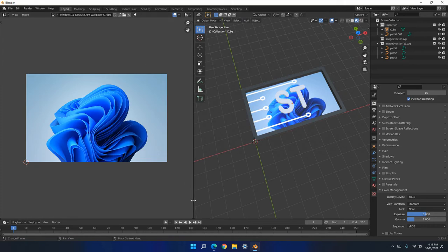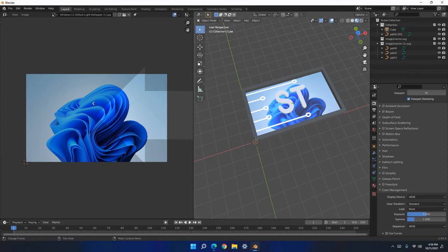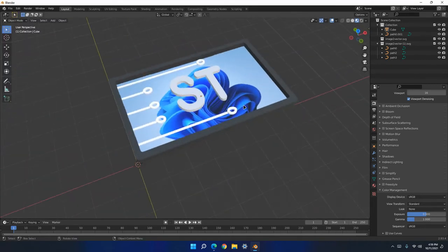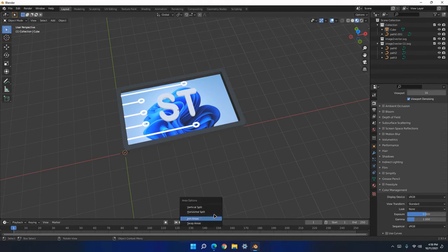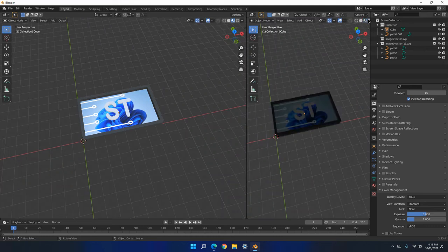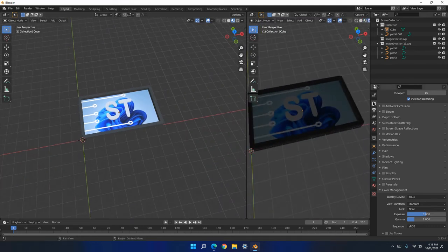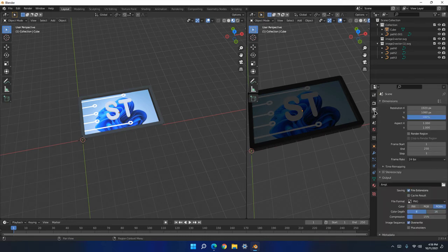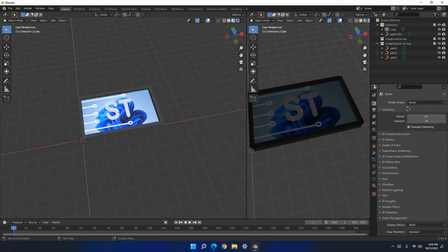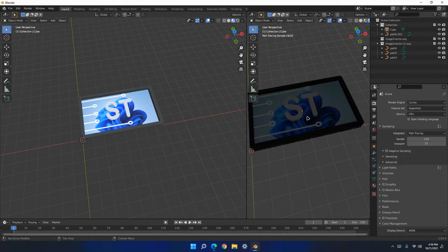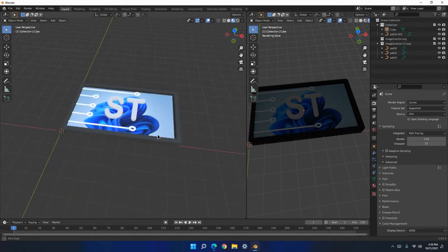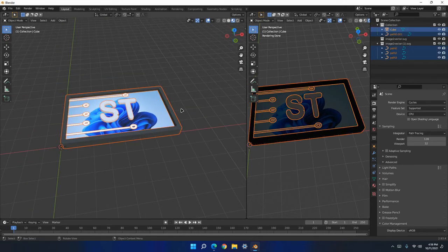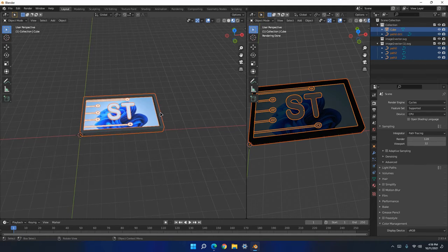Okay, now to delete this, just right click, join areas, and then you want the arrow pointing towards the one you don't want, and then click and it'll be gone. So now you want to actually add that render again, vertical split, and just click and render view. So first you want to come here into render properties, render engine. At the very top you want to switch this to cycles.